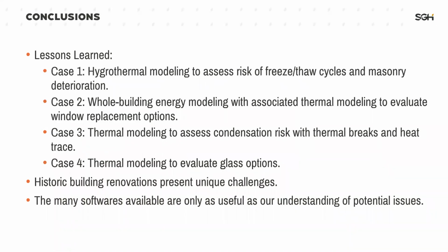So from each of these case studies, we've learned about the importance of using the correct modeling software to evaluate different risks. In our first case study, where they were proposing installing insulation on the inboard side of a multi-wide masonry wall, we used hygrothermal modeling to assess the risk of freeze-thaw cycles and the associated masonry deterioration. In our second case study, in which a client was proposing remediating or replacing existing historic windows, we used whole building energy modeling and associated thermal modeling to evaluate window replacement options.